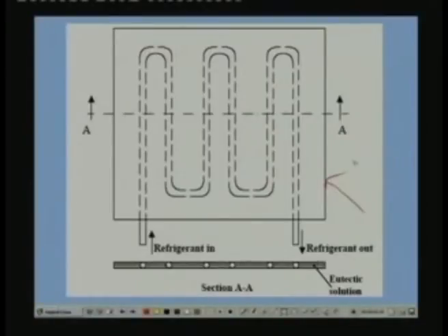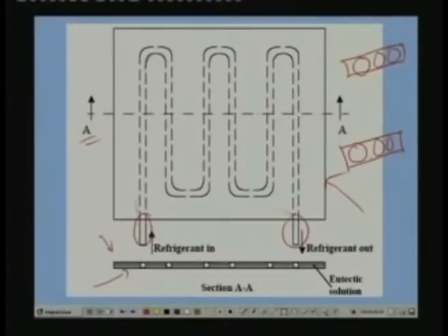and this is the cross sectional view at A. So this is like a closed box in which the serpentine refrigerant tube is sandwiched. That means you take two plates and put this serpentine coil and close all the edges, and have the inlet and outlet. Now you have some space between the refrigerant. This is the refrigerant tube. These are the refrigerant tubes, and this is the plate over which your air flows, air or whatever is the external fluid that flows.